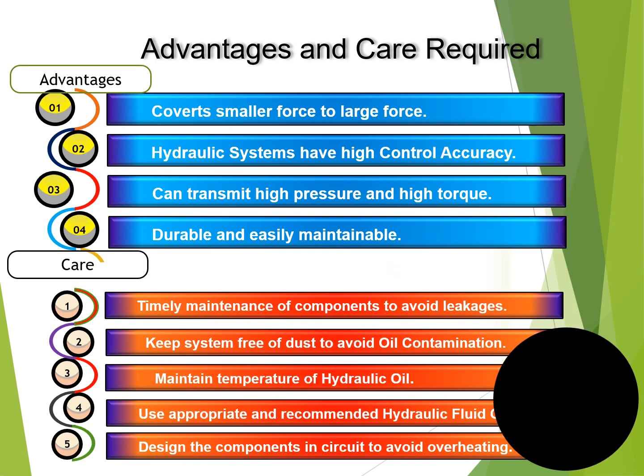So what are the advantages and care required for the hydraulic circuit? First, the advantages. It converts smaller force to larger force. If we recall Pascal's law, a force applied on one end increases in proportion to the area on the other end.